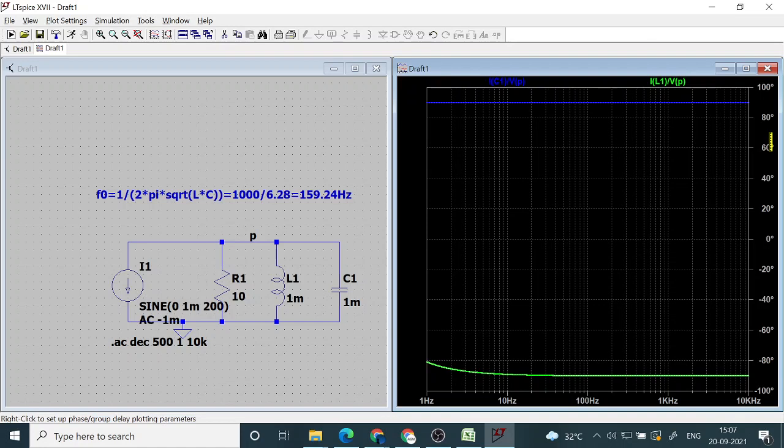All right, so that is your experiment number 2, second part. Now you will learn the theory in the network theory class, sometime. Or what you need to do is just to write down the KCL and then find out the current through individual branch. You should get an expression for whatever graph I have shown here, and that expression will have complex quantities, so it will come as a complex number which is a function of omega. In magnitude phase form you can express it to see this variation.